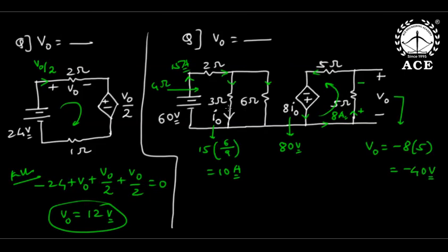See, first of all, this left side part and right side part are not electrically connected. The left side part is two meshes together, but the right side is a single mesh. Now these two meshes and the right side mesh are called independent meshes, because no current can flow through this wire, as there is no closed path. It is only a formality to give it like that.